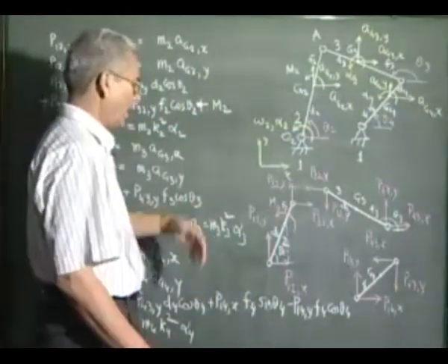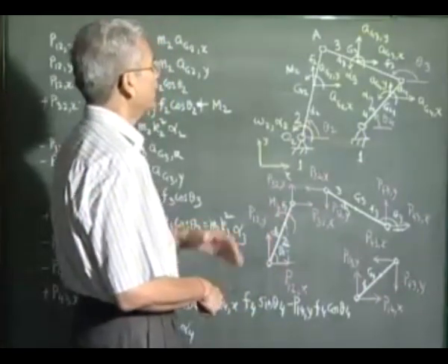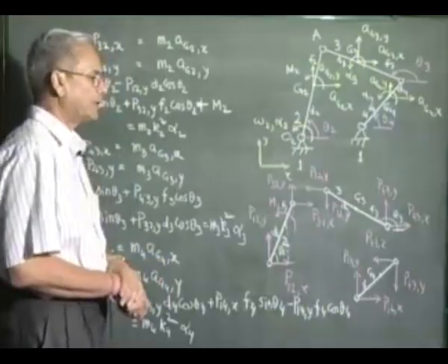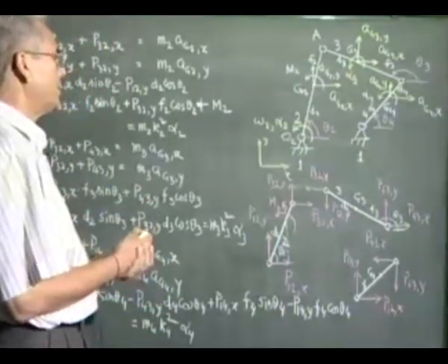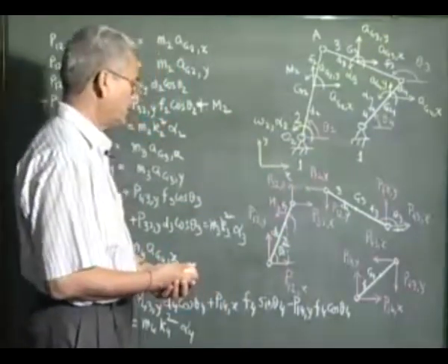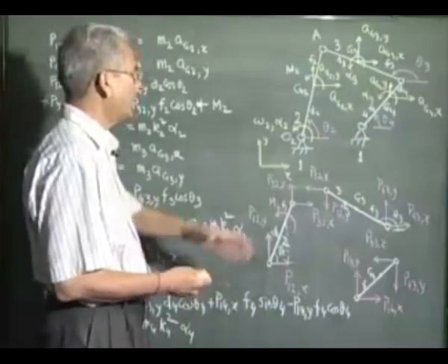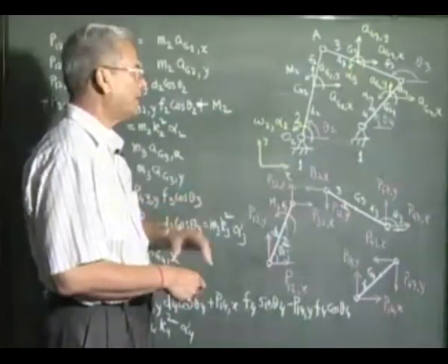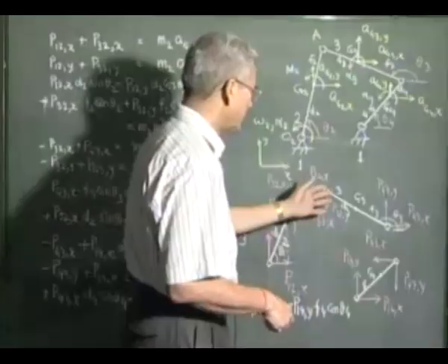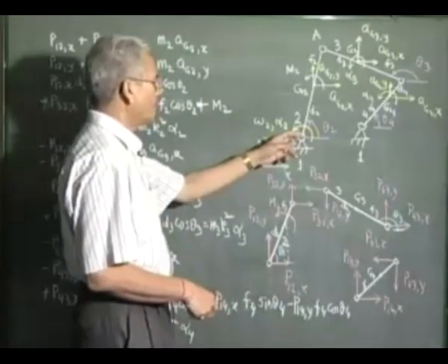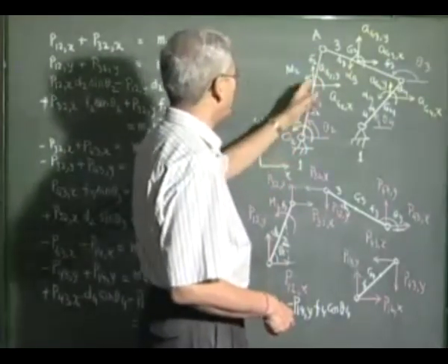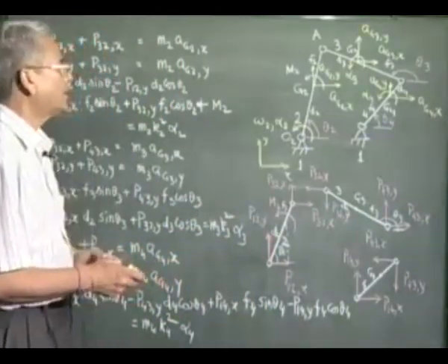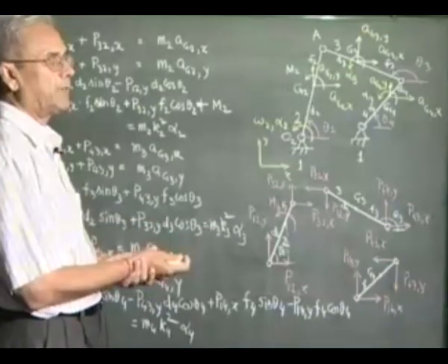There is no other limitation, and you can sometimes even solve problems keeping in mind optimization of the machines, its optimal design, minimization of forces, maximization of some other quantities, whatever it may be. In the graphical procedure, it becomes extremely difficult to repeat it hundreds of times for getting one complete cycle's analysis. Once the forces are known, a designer can design the bearings and other joints suitably so that such forces can be sustained. It is also possible, which we are not going to do here, to find out the stresses to which each link is subjected, and their design can be taken care of.